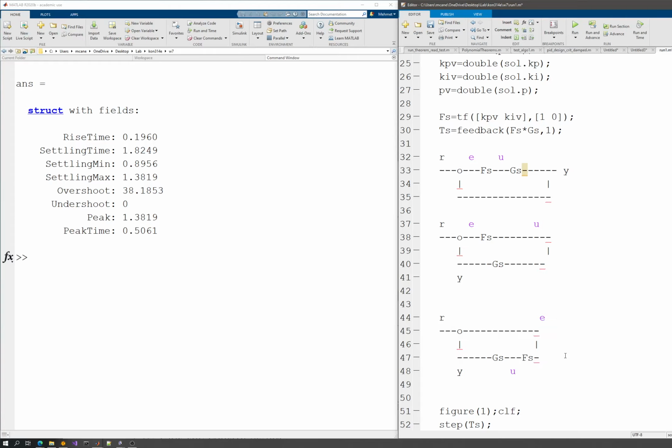So think about this. You might use Simulink to try this out, because it will give you the control effort and the error. So how can I get this closed loop transfer function? The transfer function has an input and an output, and if I choose R as an input and U as my output, I have to evaluate my transfer function. Let me call this T(s), let's say T_U, because it's relating to the output U, and I always know that my input is a reference, so T_RU can be the case, but I will just use T_U here.